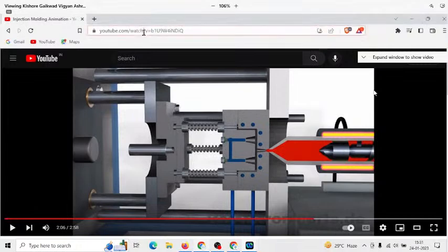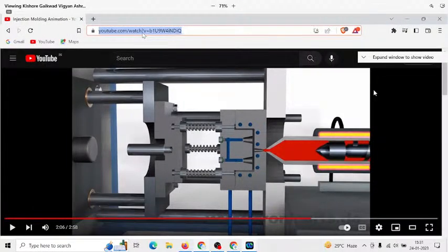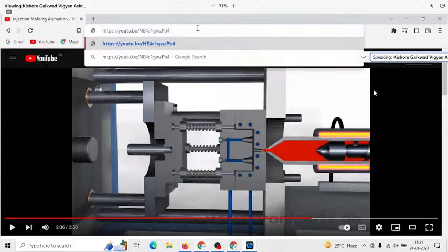So that was the injection molding process, where you could see that the plastic is melted and the molten plastic is injected into the die. The gray part that you see in the middle portion of the video is a die, and the molten plastic gets into the die and takes the shape of that die. So the final object is created. So I'm just quickly going to show you the blow molding process, where you will be able to see how plastic bottles are made using the blow molding process.